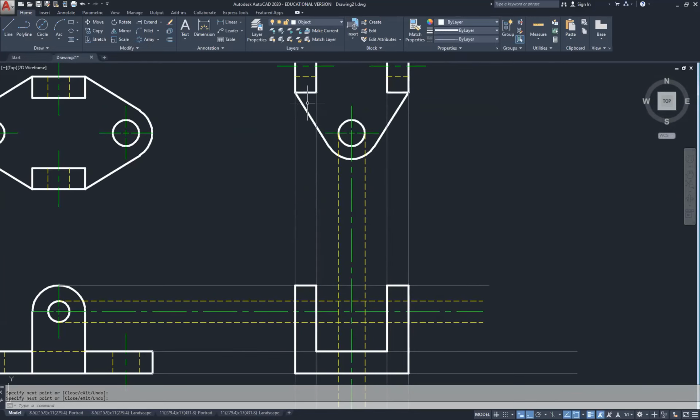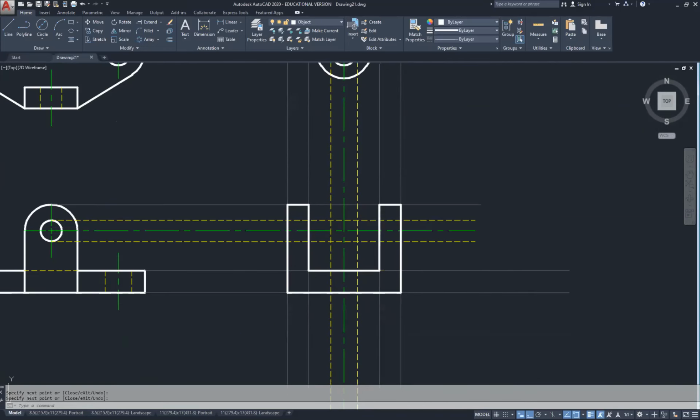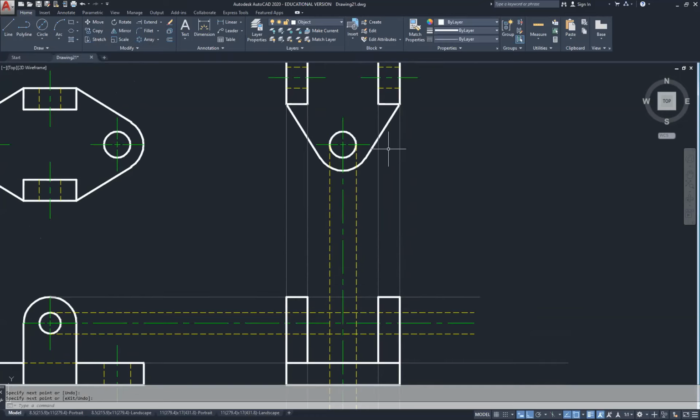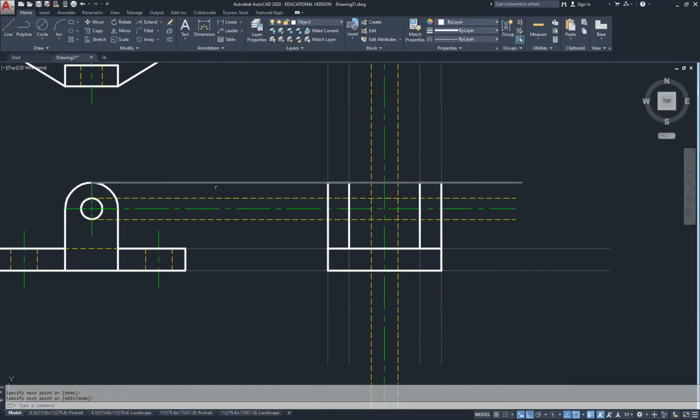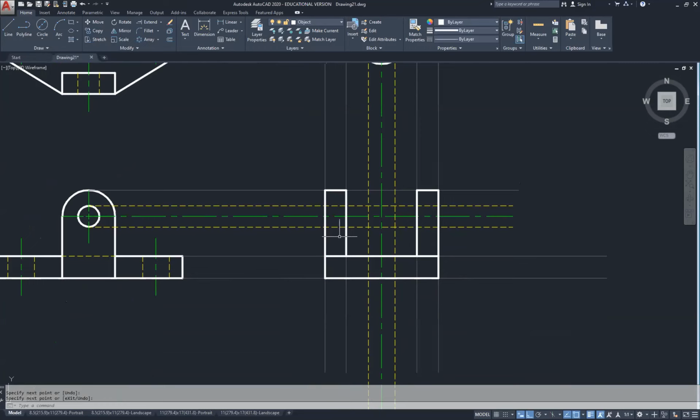Now, because this protrudes out past that U shape, we're going to need a solid line going from here straight across, and a line going from here straight across, to show that this surface area coming from here and around is a flat surface. Even though it's curved, it looks flat from this view. And then this view here, which looks flat, is the surface of this piece here.